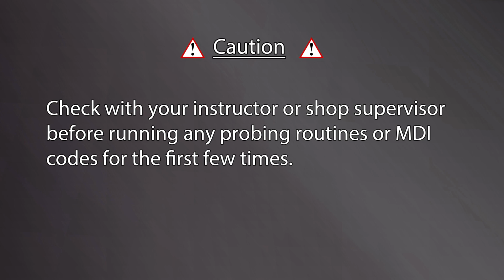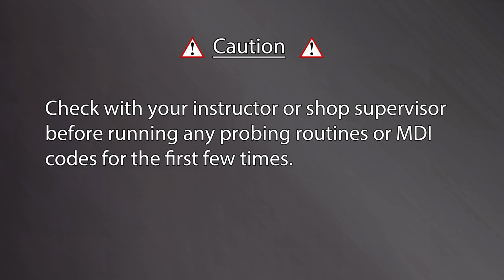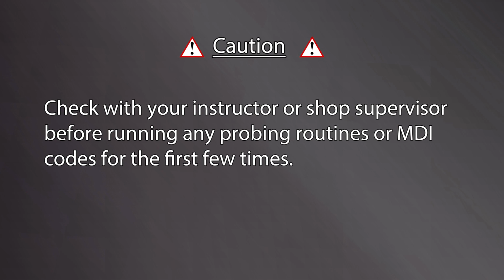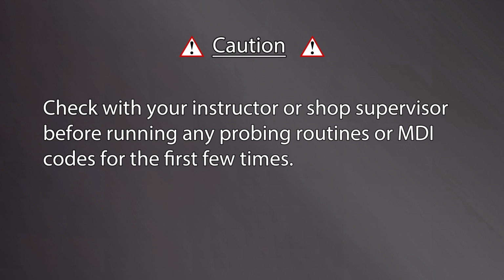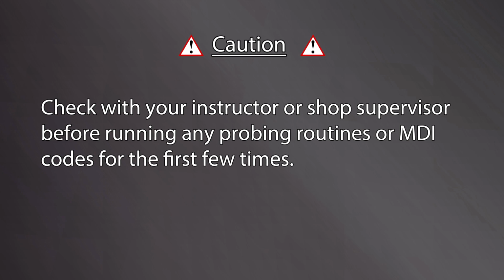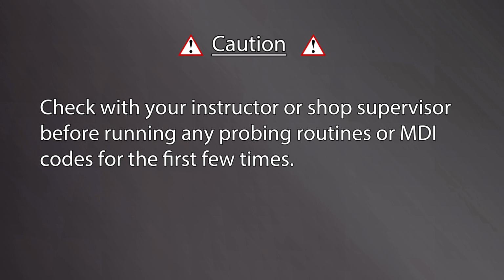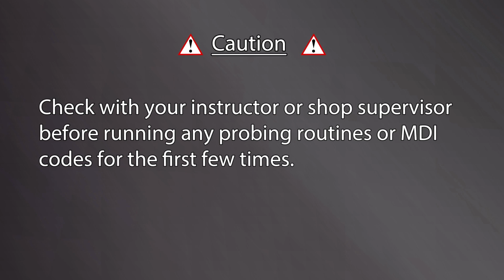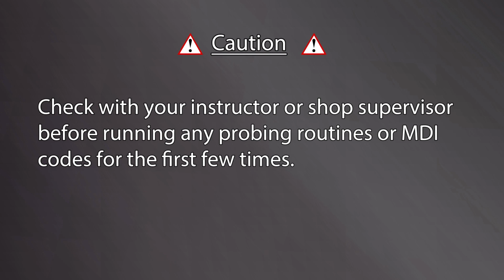After watching this video, you may feel pretty confident to begin. However, due to the fragile and expensive nature of tools, CNC machinery, and especially probing equipment, check with your instructor or shop supervisor before running any probing routines or MDI codes for the first few times.